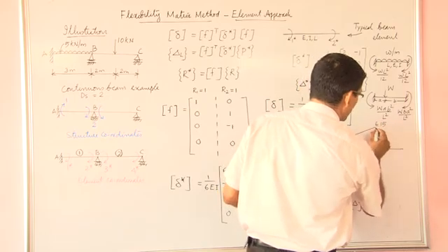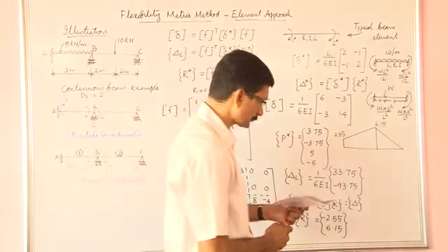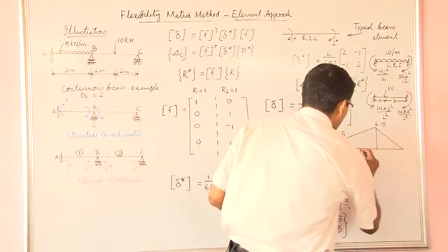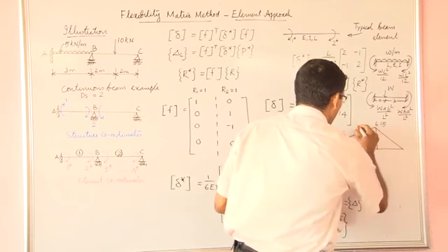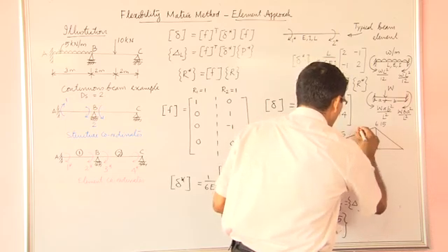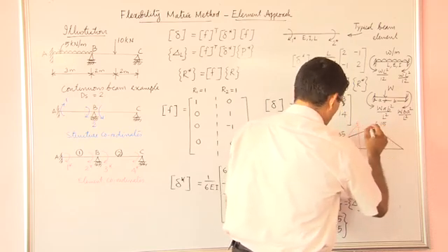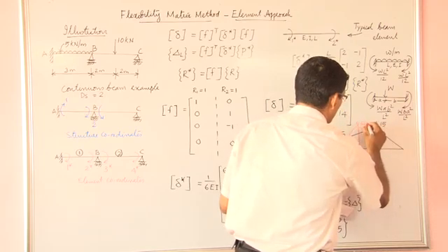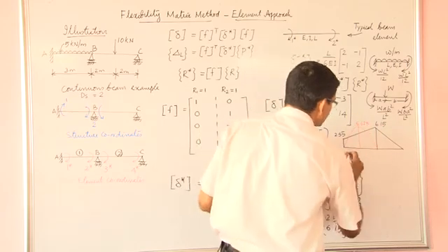Connect them. Over that, we are going to superimpose simply supported bending moment diagram. This is 5.625. Of course, the ordinate is equal to W L square by 8 for UDL.